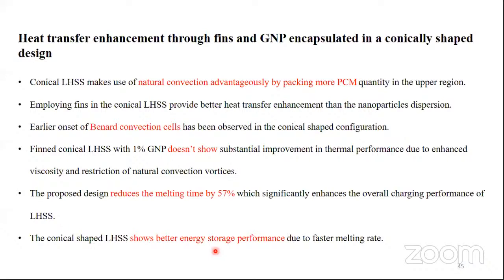And that way, the natural convection will be more predominant and will help us to get a better melting with reduced time. Now, employing PCM in this conical shape latent heat energy storage system is that it provides a better heat transfer enhancement than the nanoparticles dispersion.